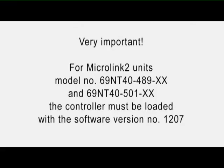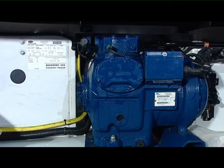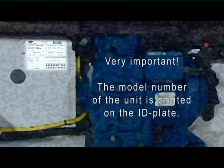Very important. For microlink 2 units, model number 69NT40489 and 69NT40501, the controller must be loaded with the software version number 1207. For microlink 2i units, model number 69N24511 and 69N24521, the controller must be loaded with the software version starting with number 51. The model number of the unit is printed on the identification plate.